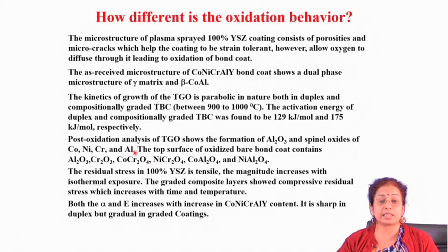Post oxidation analysis showed a lot of spinels, which actually help in reducing the kinetics of oxidation further, or increase the activation energy of the oxidation. Residual stress is also reduced to a large extent and changes from tensile to compressive because of the graded layer formation.